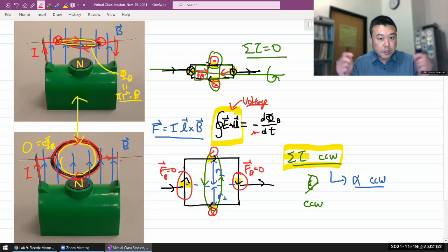There's an induced voltage in this coil that's going to oppose the voltage that you are applying. So there comes some equilibrium speed where the applied voltage equals the induced voltage that's opposing it. And at that point, the whole thing is not going to draw all that much current. If you imagine a frictionless, perfect motor spinning frictionlessly, then there's an equilibrium speed where the coil won't be drawing any current because the voltage you are applying is precisely opposed by the back EMF.